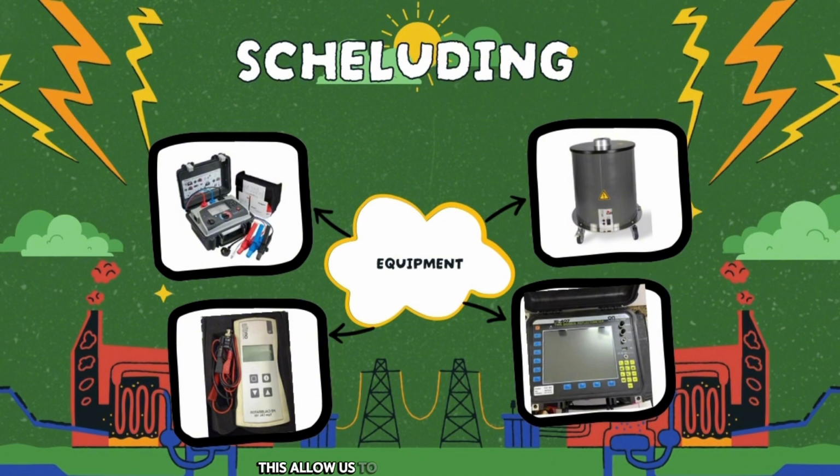This allows us to map out total cable length and pinpoint the exact physical location of cable faults and joints down to the meter.